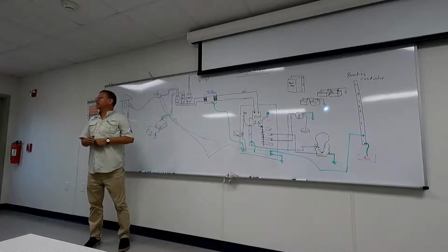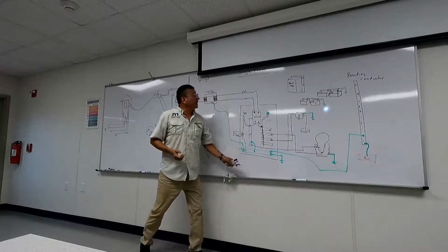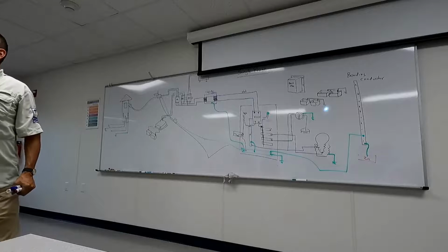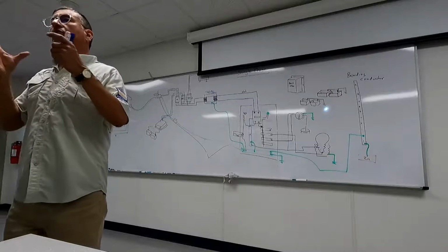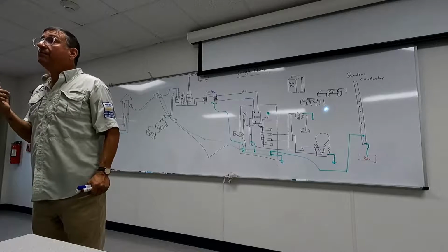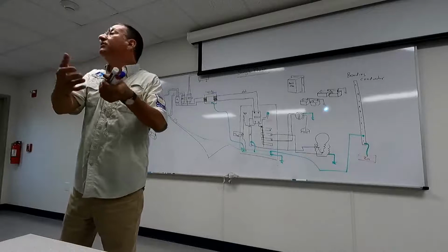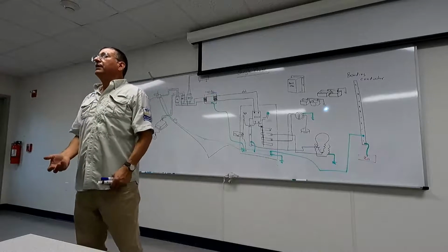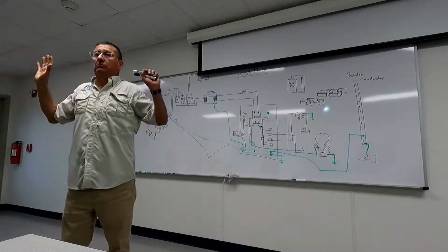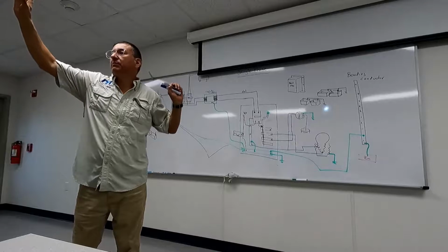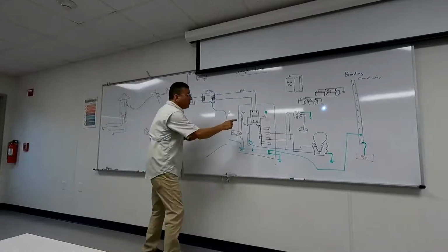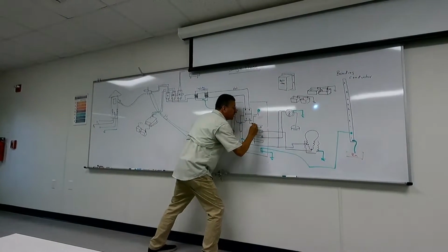Follow me because we don't have too much time. Good. We are going to connect the battery charger. Where is the power coming into the battery charger? The power in is AC power, and the power out is DC to charge the battery bank, no? The power in is coming from the AC panel. It doesn't matter if the AC panel at that moment is powered from generator, inverter or shore power. It's AC power. I have one breaker here. The breaker is for the battery charger.